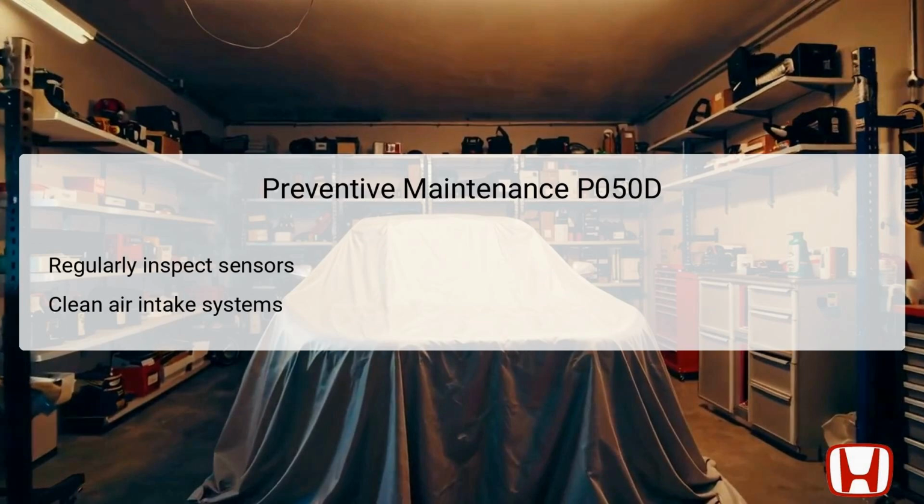Preventive maintenance is crucial for avoiding issues related to DTC P050D in the future. Regularly inspecting sensors, including the MAF and IAT, can significantly reduce the likelihood of cold start idle issues. Consider scheduling routine diagnostics that check for fault codes as part of general vehicle upkeep.